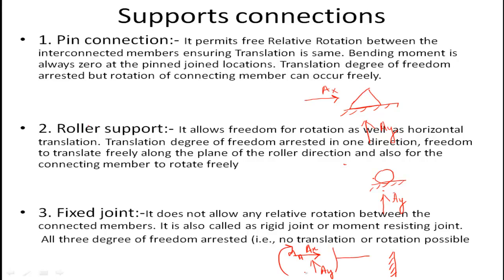Often it's misconstrued that a rigid joint implies no deformation. It must be clearly understood that the rigidity here refers only to the joint. The structure itself is deformable. The rigid joint can translate and rotate, but it will do so always ensuring compatibility of displacement of the ends of the connecting elements at that joint.